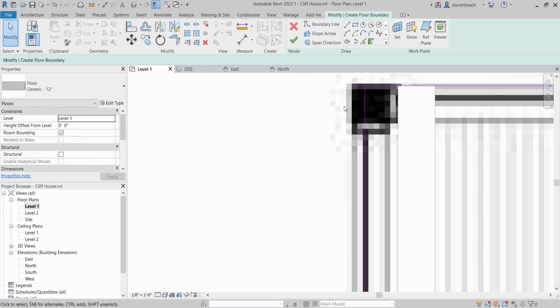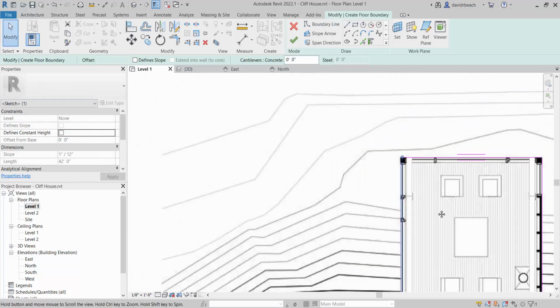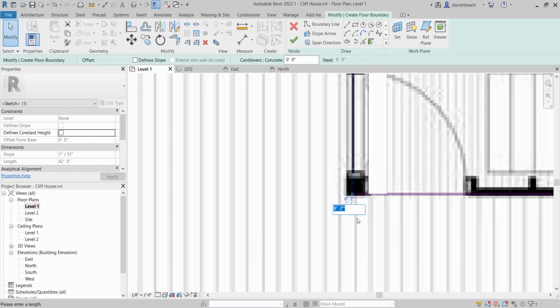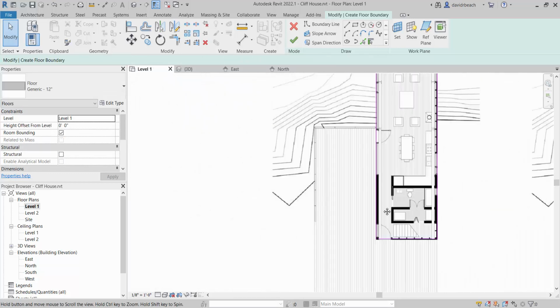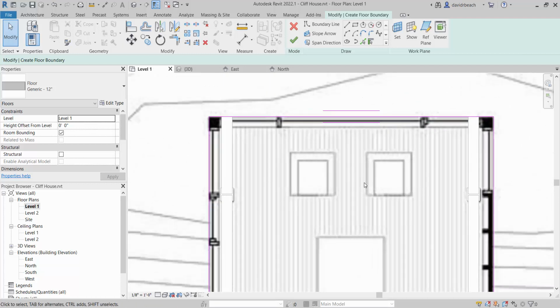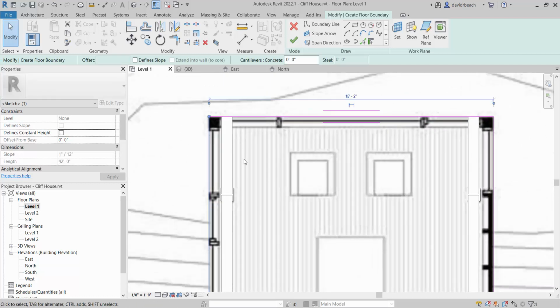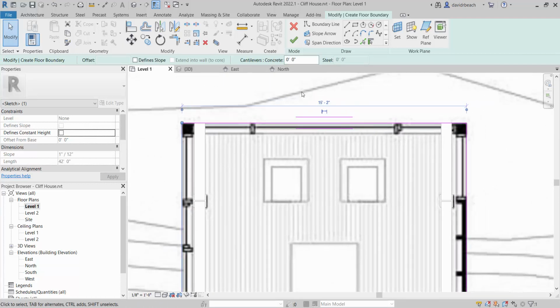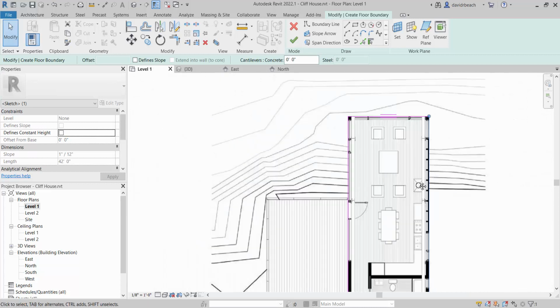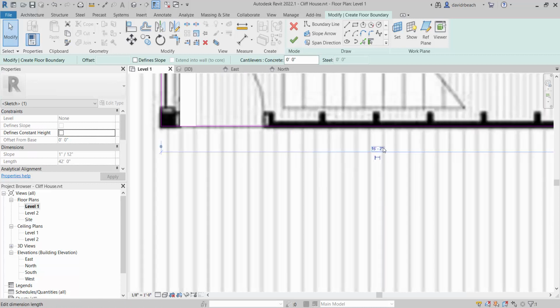And then I'm going to connect that together. It looks like 15 feet is just a bit shy. So I'm drawing that at 15 feet, 2 inches, right? So I can check those dimensions anytime that I'm drawing. Like if I just select one line in my floor, right? If I select this edge, again, it's going to give me these temporary dimensions.